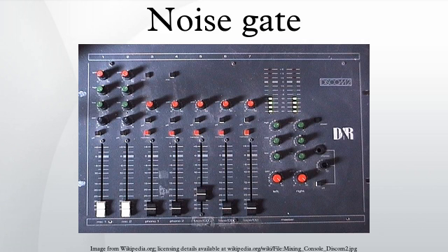A noise gate, or gate, is an electronic device or software that is used to control the volume of an audio signal. Comparable to a compressor, which attenuates signals above a threshold, noise gates attenuate signals that register below the threshold. However, noise gates attenuate signals by a fixed amount, known as the range.